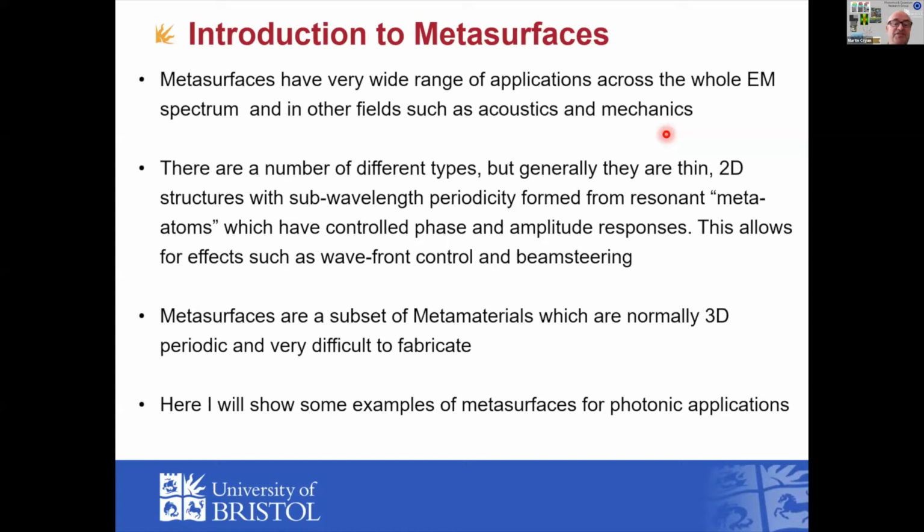So these things, metasurfaces, they're actually a subset of a larger field, if you like, known as metamaterials, which again, some of you may have heard about. One of the big problems with metamaterials is they're typically three-dimensionally periodic structures, and that can be really challenging to fabricate. So the big advantage of metasurfaces is, in principle, they're not too different from making PCBs or making silicon chips that you might find in your phone. So they're very amenable to fabrication.